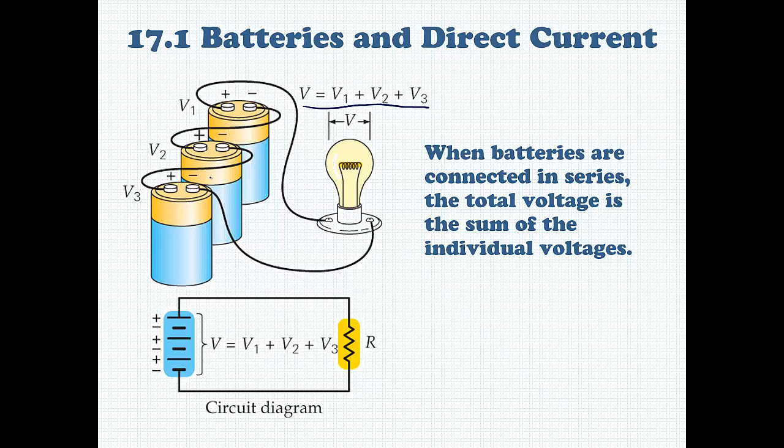This is why in calculators and other devices you get a number of batteries adding together. And so in the case of a Texas Instruments graphical calculator, if you look inside the battery case there, you'll see 4 AAA batteries. Those are all 1.5 volt batteries. And when they're arranged as they are in a calculator, they are in series, and therefore they are contributing 6 volts.